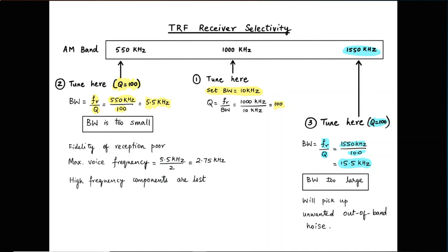So I hope you see that selectivity, by this example, you see that if I made the filter selective, I was not able to do the tuning. But if I made the thing very tunable, I would not have been very selective. So there is an inverse relationship at play with respect to these two aspects of tunability and selectivity of a bandpass filter that are resolved in a superheterodyne receiver, which actually gets benefits of both. And we do that by doing it in stages. Let's do tunability first and then focus on selectivity. So we get the best of both worlds by doing that.